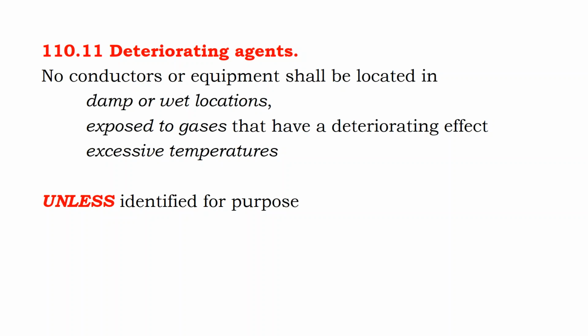Now the rooftop is a wet location, but it's also subject to extreme temperature. We're going to get into temperature ratings in the program, and there's going to be wires listed for 75 C temperature and 90 C temperature. You might ask yourself, okay, I'm using a 75 C temperature calculation, and my wire is well sized, and I have the amperage in it. Do I need to be using 90 C wire if my 75 C wire has sufficient amperage?